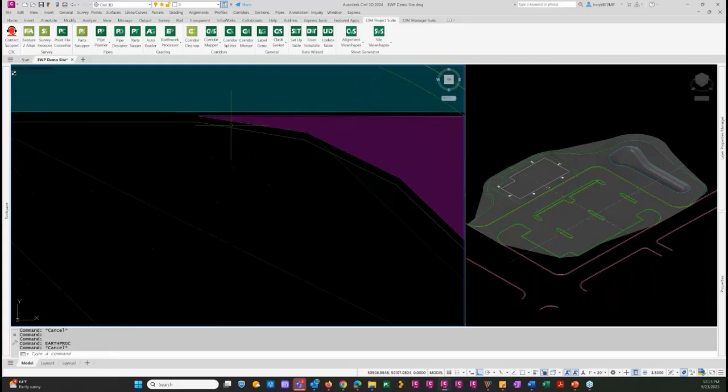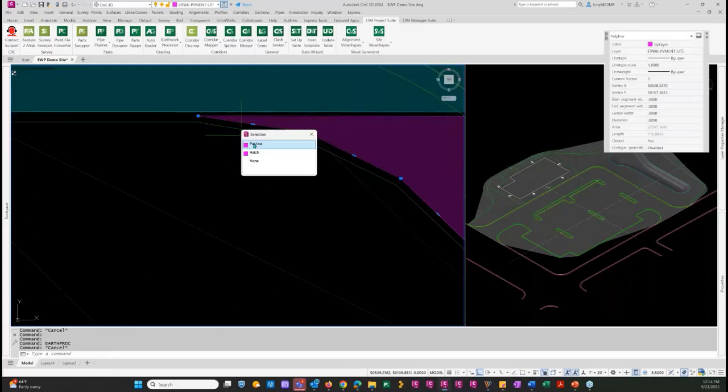Let's do this pavement light area. So it's the polyline we're concerned about. And you see the elevation here is 0. So we're going to come down 1.5, a foot and a half for that one. So I'll give it 1.5.